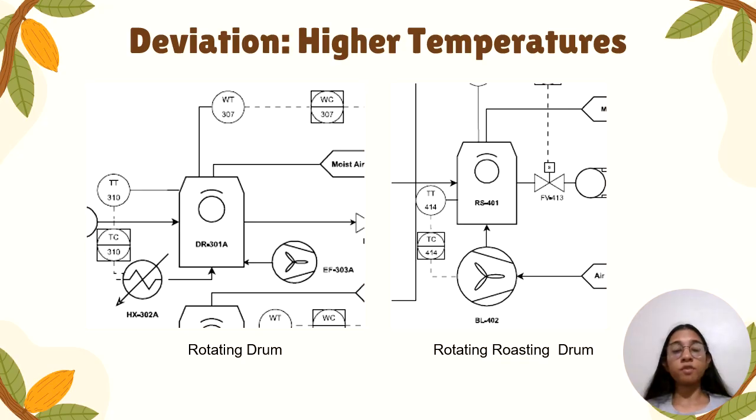Multiple machines involve the use of temperature control. Factors that can cause higher temperatures include temperature control malfunctions, faulty temperature sensors, heating element malfunctions, or exhaust fan malfunctions. These can cause the heating element to provide excess heat or affect the efficiency of the exhaust fan.